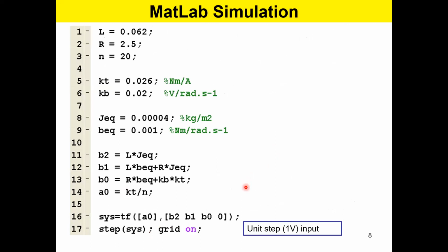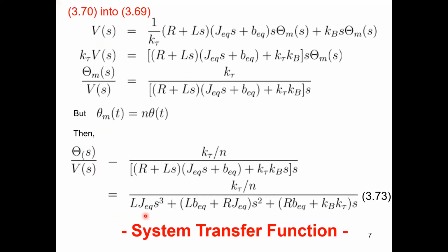So in MATLAB, this is how we declare our transfer function, because the transfer function command is there. You use TF and within brackets the numerator polynomial over the denominator polynomial. So the numerator polynomial is just A0, that is this one. You only write the coefficients of the polynomial.